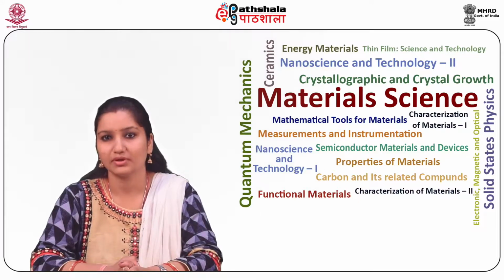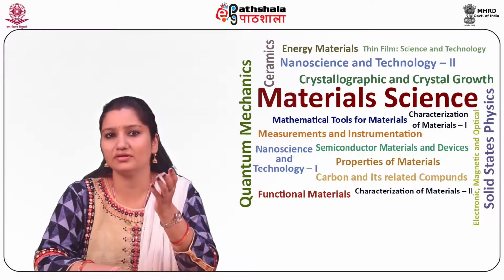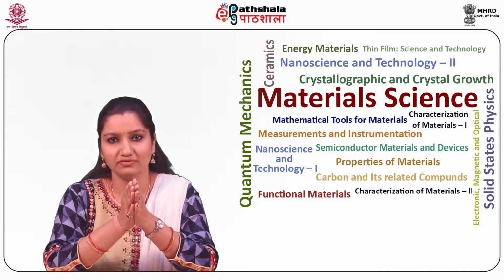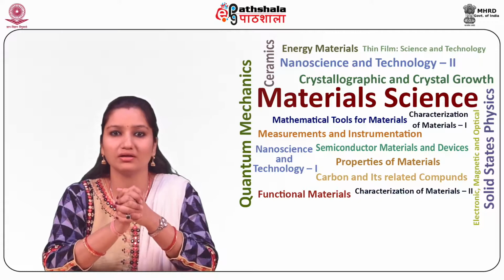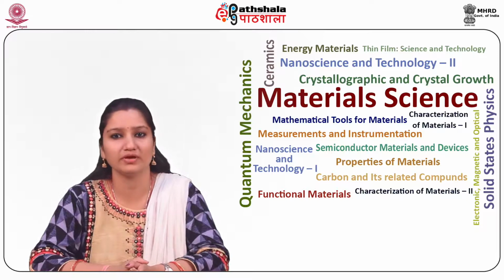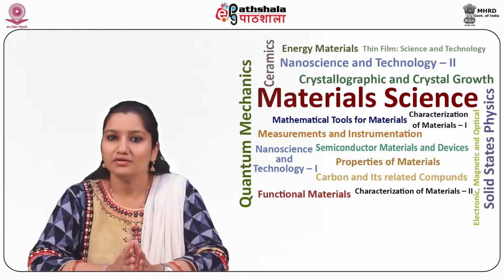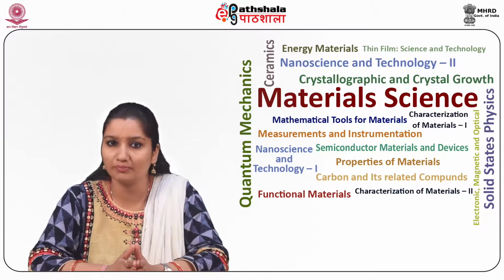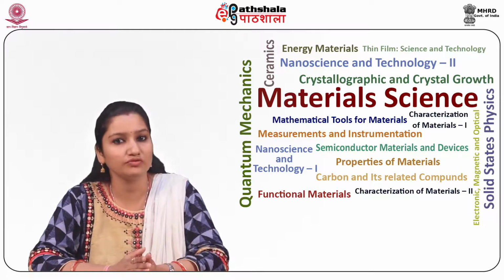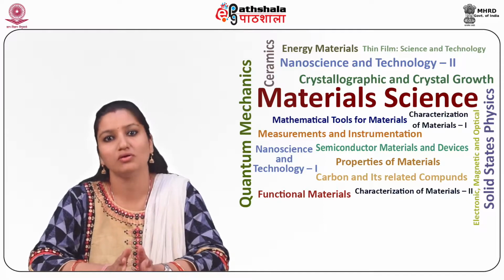The bombardment often leads to an increase in the density of the film and helps to remove contamination, thus improving the film's electrical and mechanical properties. When high density plasma is used, the ion density is high enough such that significant sputtering of the deposited film occurs. This sputtering can be used to help in making the film planar and fill troughs and holes.